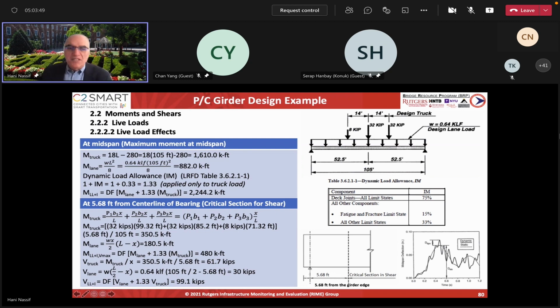So this is at mid-span, so this is one section. And if you recall, because there's interaction at every section of the span, there's the moment and the shear, one increasing and one decreasing. There will be a point where the shear is critical. And if the 10-10 is draped, in other words, harped, some of them go towards the top of the girder, some continue straight, then the center of the steel is going to go up. That means when it's inclined, the prestressing force itself will resist the shear.